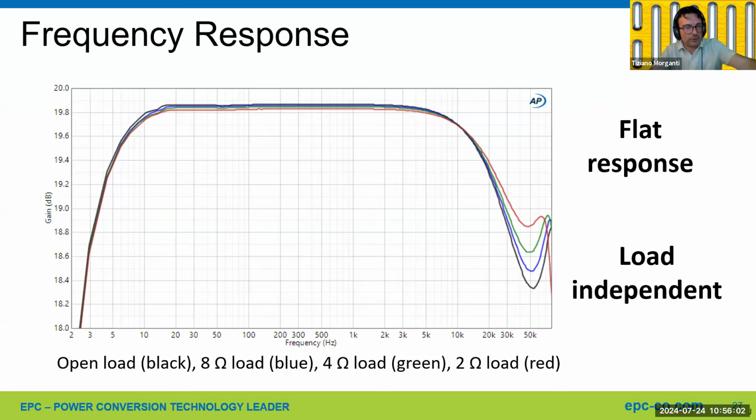Actually, it's one of the things we need to improve to increase our efficiency, because we now have the high frequency capacitors are 10 nanofarad, 0603. They might drop to maybe 3 nanofarad each at high voltage. But there are 4, so we have 12 nanofarad that is just dealing with the switching transient. So it's enough capacitance because the switching transient is lasting nanoseconds.